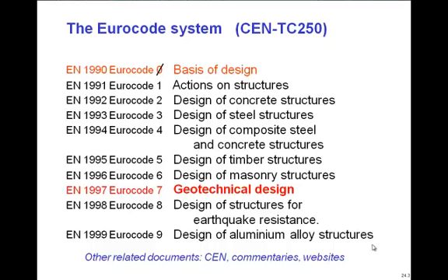Firstly, the Eurocode system itself. The Eurocodes are a set of design codes written for standardizing the design of buildings and civil engineering structures. As we'll see, there are other codes that relate to construction, but these are the design codes. Eurocode basis of design, they don't like it to be called Eurocode 0, sets out the general principles of the system and provides all the definitions of terminology, so it's important that anybody working with the Eurocode system has basis of design available to them. Much of its information is not repeated in the other codes.